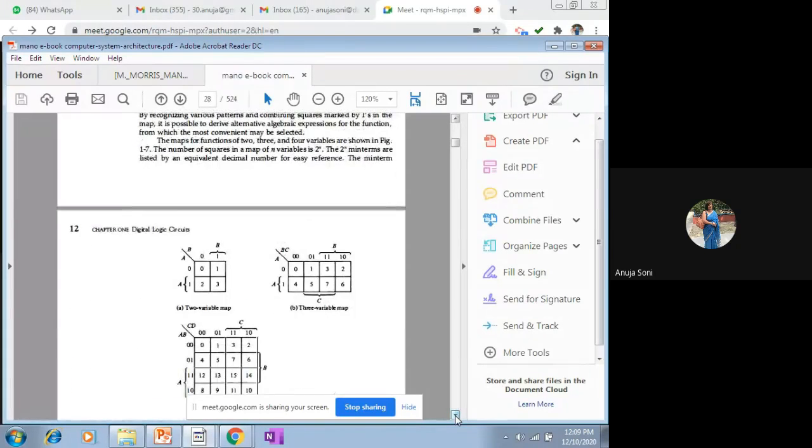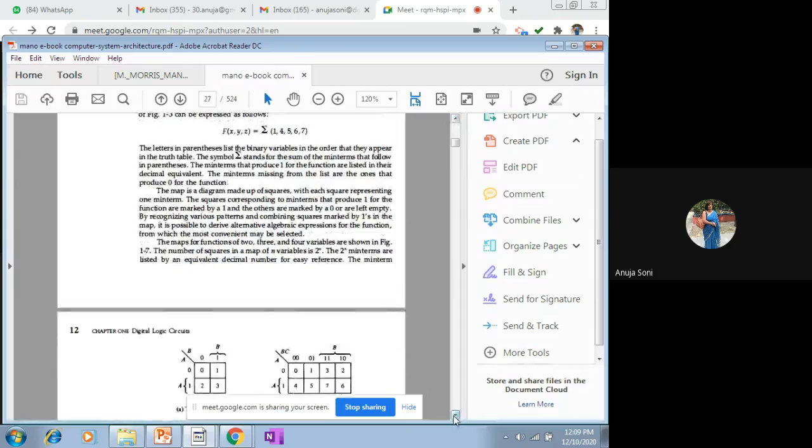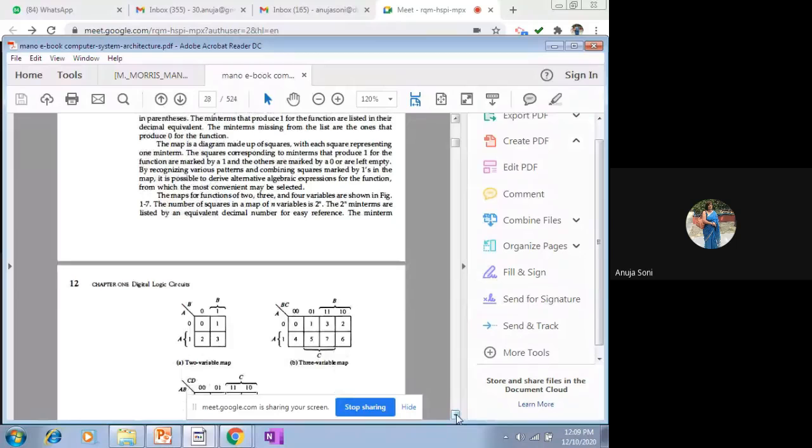So wherever there are three variables, in that K-map 8 min terms are being used. This K-map corresponds to this expression. Within the cells, the decimal values of the input variables are written. And outside, above, on the borderline of this rectangle, the different input variables are represented. On one side A, on another side BC, because here we are saying three input variables.